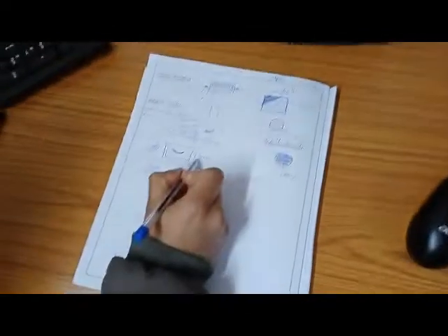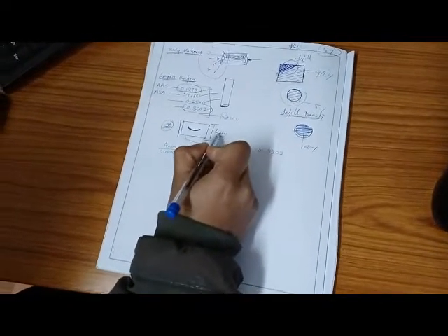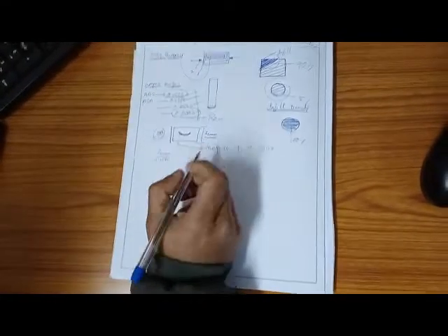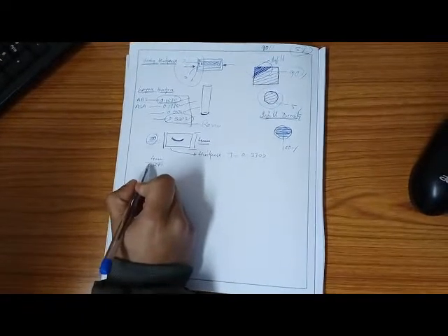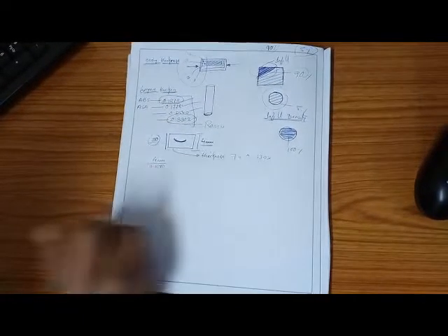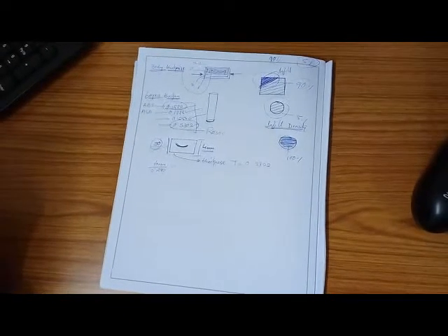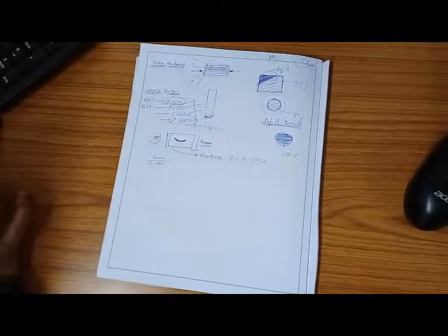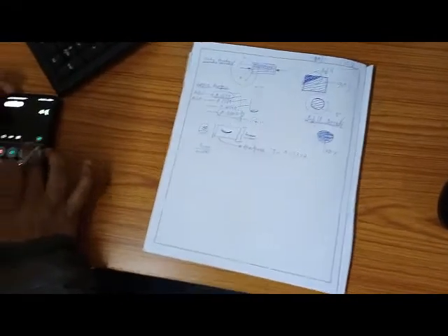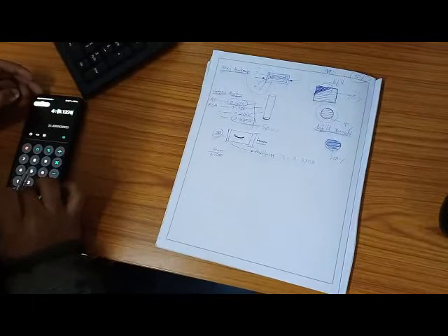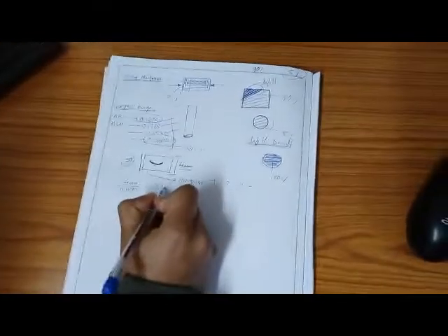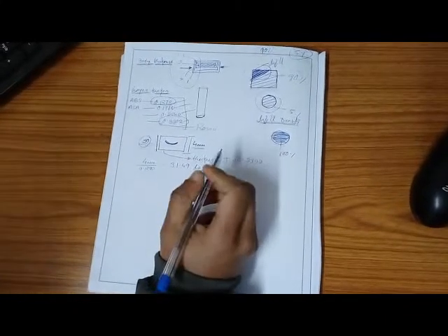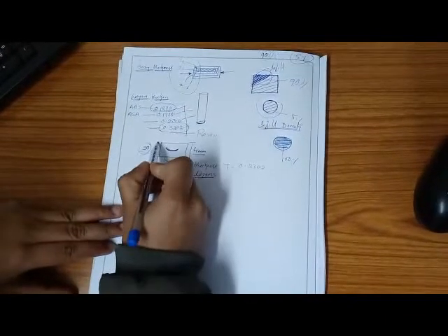But if the total length of this specimen is 4 mm, how many layers will we have? So what we will do is that 4 mm, the total thickness, divided by the resolution, will give the number of layers. So let's check what value we find here. So 4 mm divided by 0.1270. So we'll have here 31.49 layers. So even in the software we can find how many layers will form here.